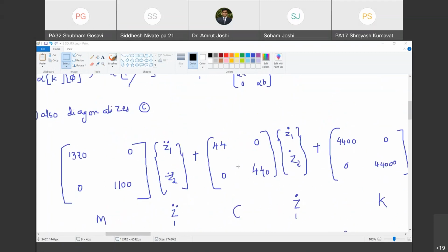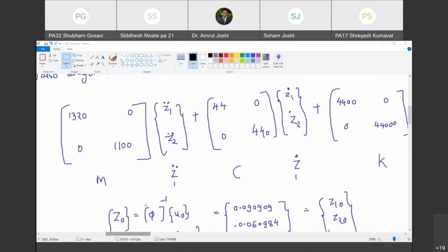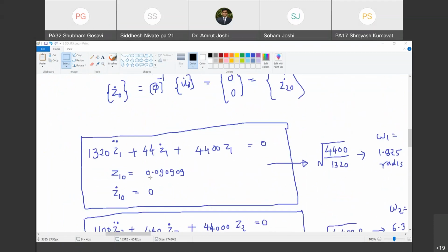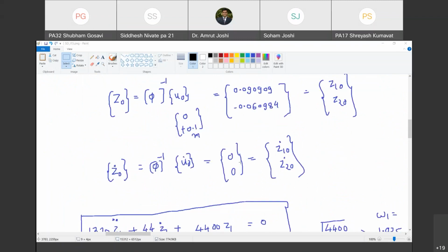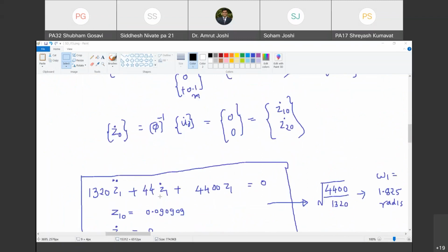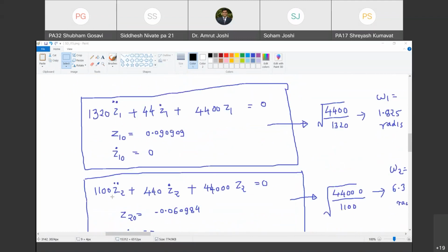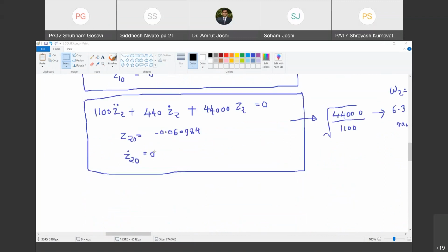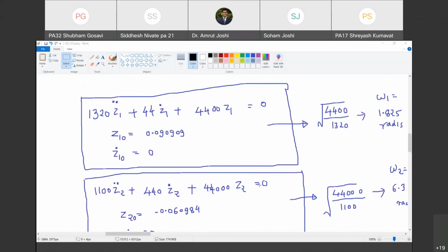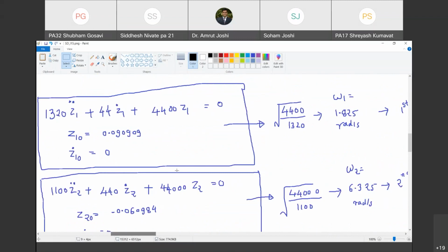and we have two differential equations. So we have expanded the first row, and we got this first differential equation with the first set of initial conditions. Are you with me? Yes, sir. Then we expanded second row, we got the second differential equation with the second set of boundary conditions. And then looking at its similarity with the equation of motion for single degree of freedom system,